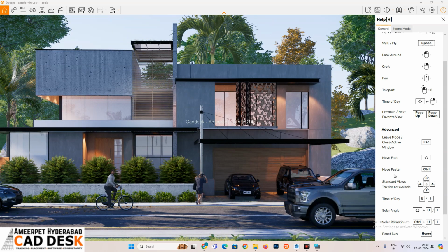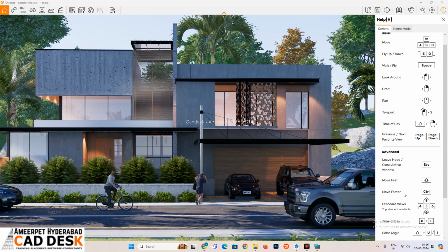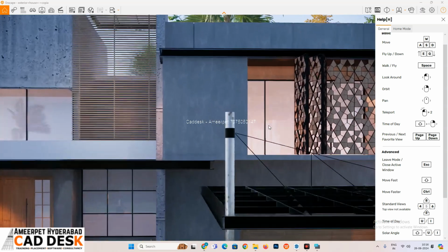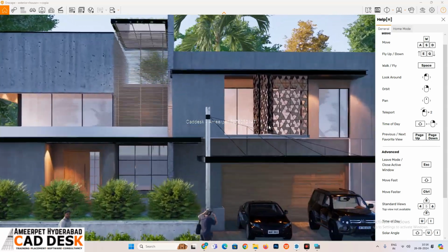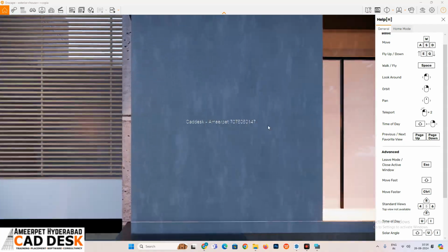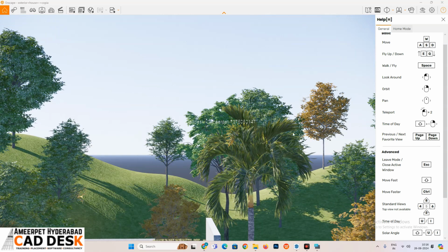And the next one, this speed also sometimes it is not enough. Even I want to move more speed now. If you want to move more speed, now you have to hold the control. Instead of shift button, for any letter or any arrow, parallelly, if you take the help of control button, now the camera will move very fast. See now, I'll hold the control, then I'm using this one. Compared to fast, now it is going very fast. See like this. It means faster. Maybe right side, left side, up and down.